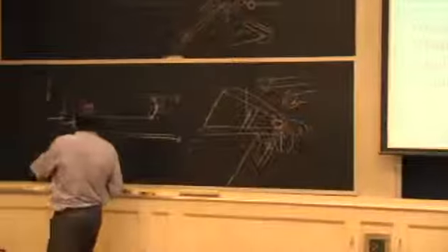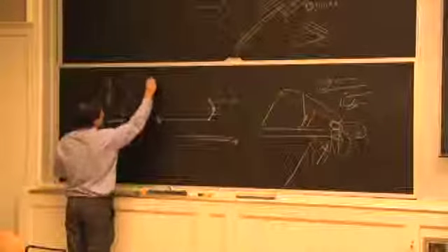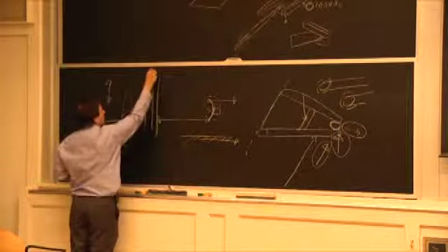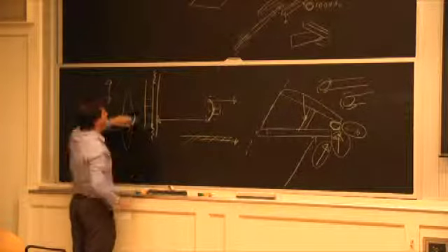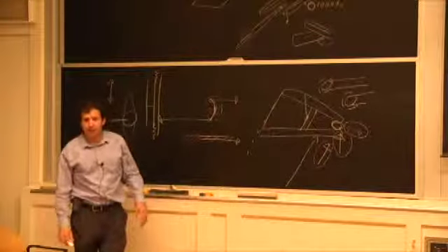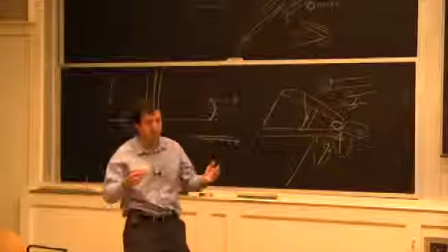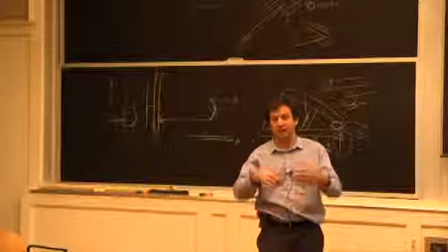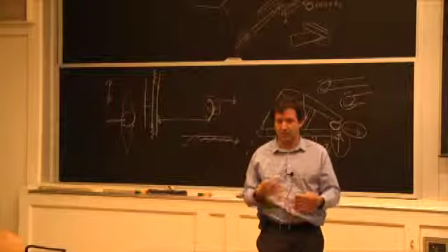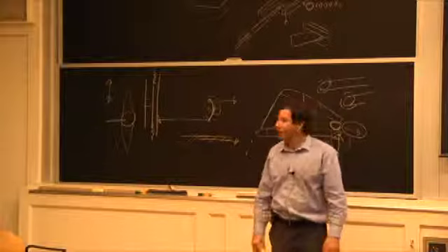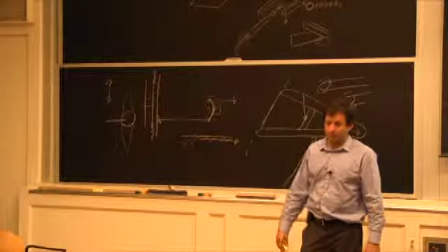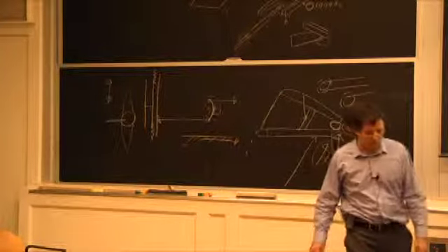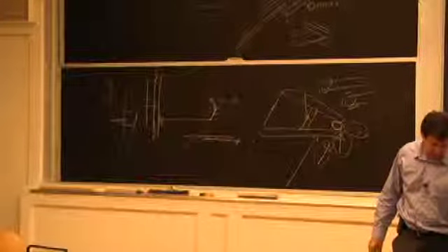If I stiffen the hole, so I have a plate like this with the hole, and I come and just put another member that I weld here and here, I don't want to increase the stiffness of the system too much, because it's still supposed to work by deforming back and forth. It needs to have compliance and energy absorption. That's the design requirement. So we did find a way, but it wasn't to say, well, let's make it look the same. Because in terms of property, that was really the worst case scenario.